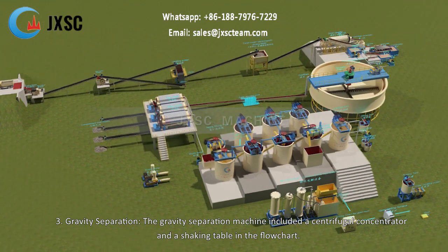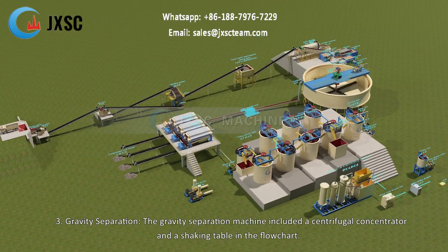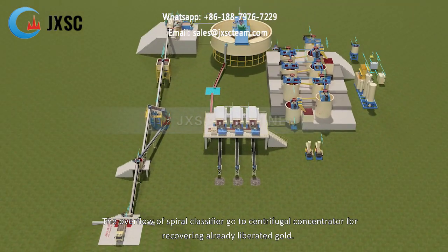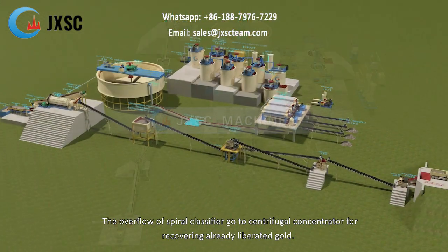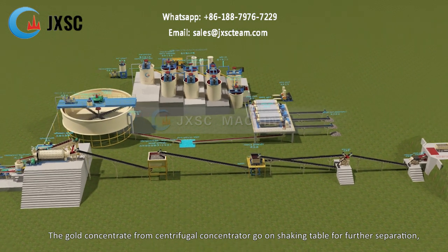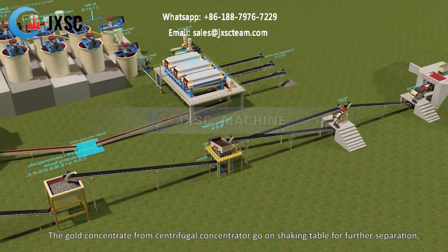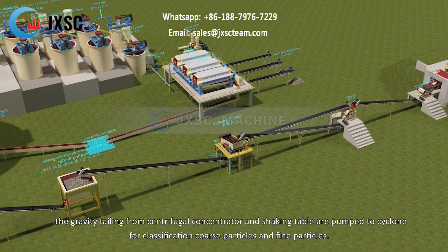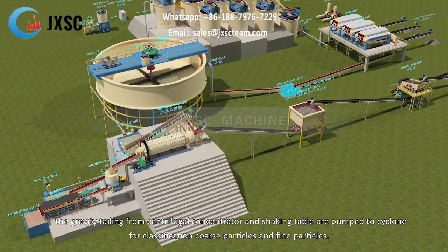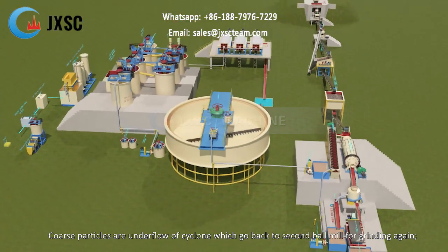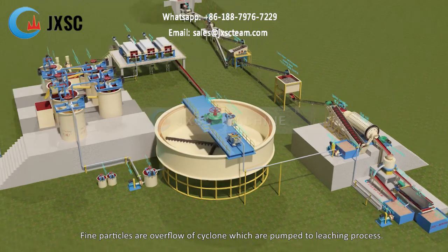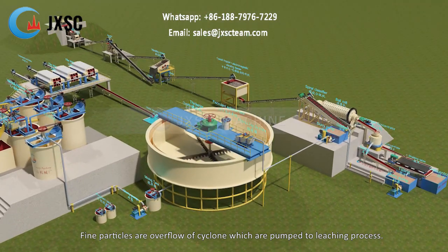3. Gravity separation. The gravity separation machine includes a centrifugal concentrator and a shaking table in the flowchart. The overflow of the spiral classifier goes to the centrifugal concentrator for recovering already liberated gold. The gold concentrate from the centrifugal concentrator goes on the shaking table for further separation. The gravity tailing from the centrifugal concentrator and shaking table is pumped to a cyclone for classification into coarse particles and fine particles. Coarse particles are the underflow of the cyclone, which go back to the second ball mill for grinding again. Fine particles are the overflow of the cyclone, which are pumped to the leaching process.